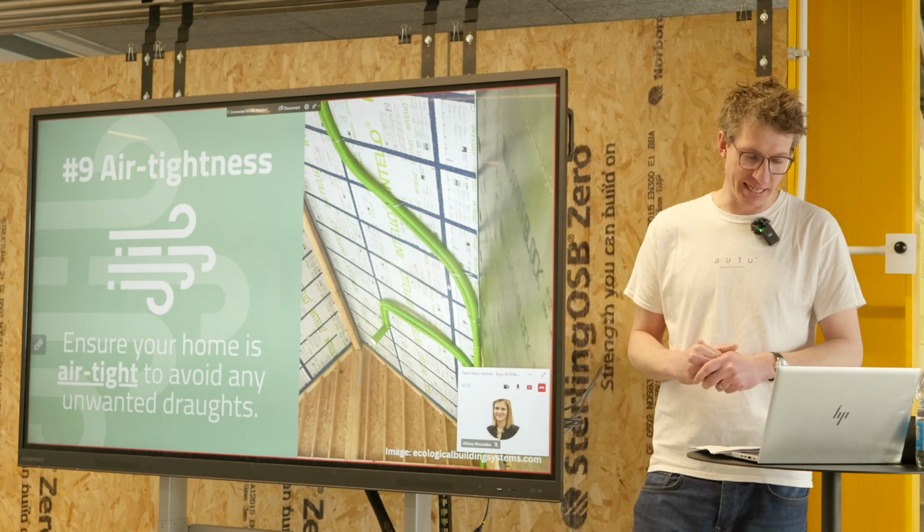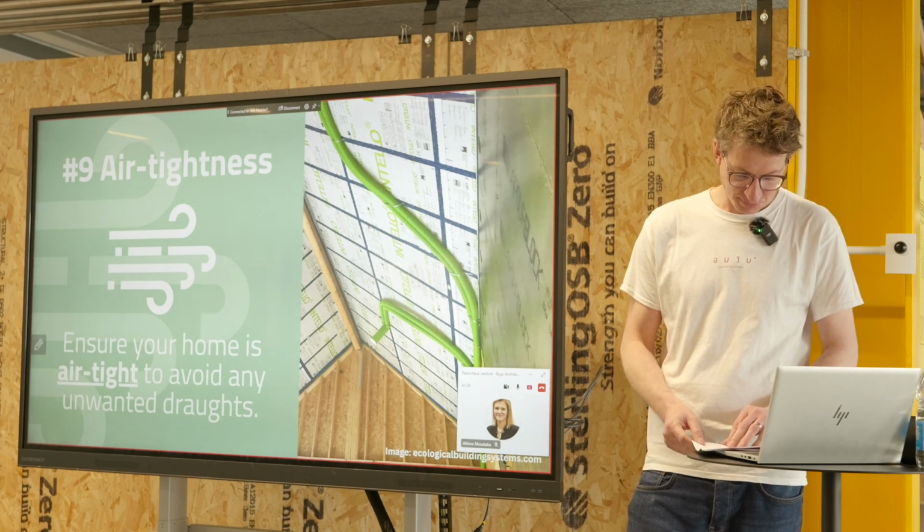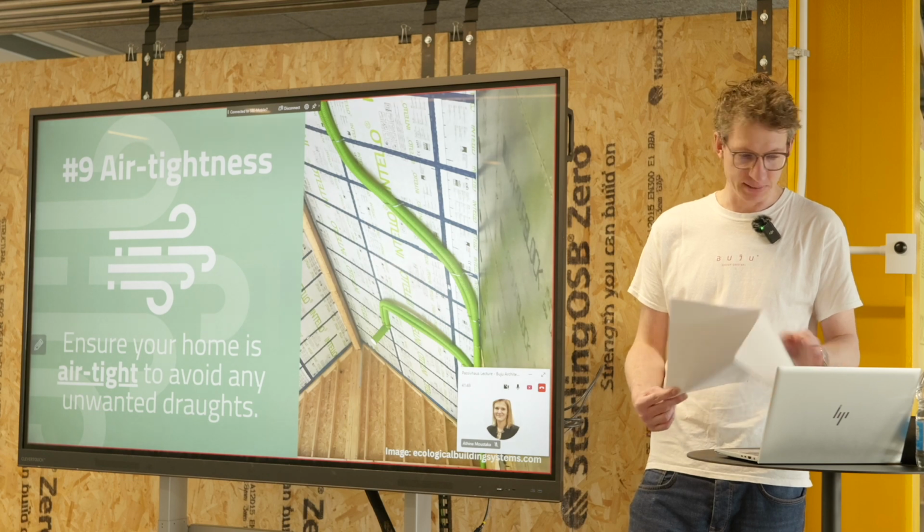So airtightness is a really important part of it, and obviously these things add a bit to the cost as well. So it's worth getting it in there really, so everyone's on the same page. Usually the airtight layer is on the warm side of the insulation as well.